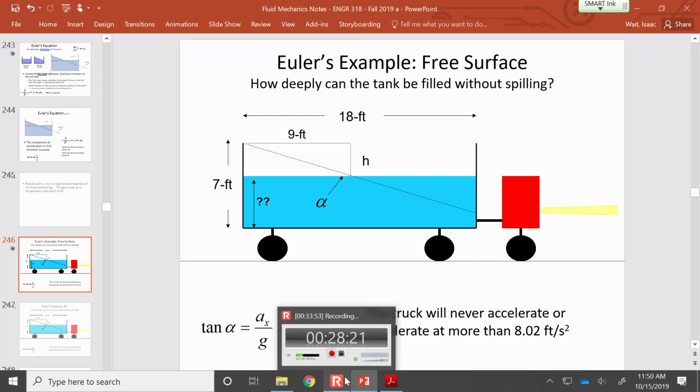When we get together on Thursday, we're going to start discussing an equation that tells you how the pressure changes when there is non-uniform flow caused by convective acceleration. For that, you're going to use Bernoulli's to predict, same thing, the delta P. So acceleration causes changes in pressure that are different than the hydrostatic equation. That was your first equation that predicted change in pressure.